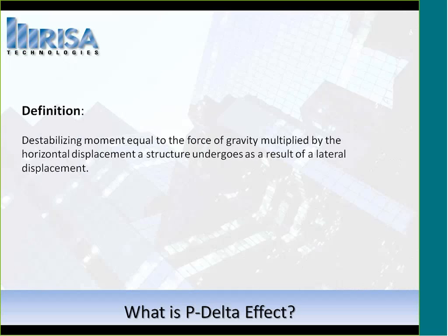Really what that breaks down to, and the name P-Delta is really the definition, P is the force of gravity, and you multiply that by the delta, or the horizontal displacement. We also call this sort of leaning column, but what it's really addressing is how the force of gravity is going to be causing displacement, and how that affects the stability of the structure.